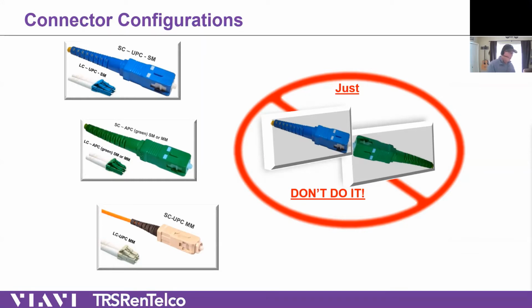It works very good in lower distance connectors. But because it is a flat connector, it causes some reflection issues. So they've come out with the angle polish connector, the green one. So what does the angle polish connector do? Instead of it rounded like a baseball, they cleave it off at an 8-degree angle. So it's like a knife blade, right? So you get your fiber up and then they slice it off at an 8-degree angle. That way, when you plug 2 greens in, the glass is not 90 degrees to each other. It's actually shifted off by 8 degrees in either direction. And that actually helps a lot, which I'll show you on the next slide, for how an OTDR works and how your network works.